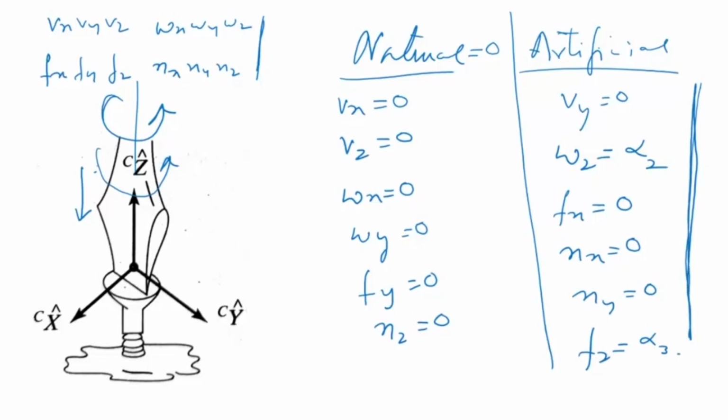So how can you do this? We have to control all these variables. So 1, 2, 3, 4, 5, 6 variables have to be controlled here to perform this task, and hence a robot would find it very, very difficult to tighten a screw. If you see industrial robotic applications, very, very often a robot cannot do tasks where there is contact, and that is one problem with robots, because you need to control too many artificial constraints, and some of these are constrained in the sense that the position and forces are orthogonal again. So there is one more constraint actually which is coming.